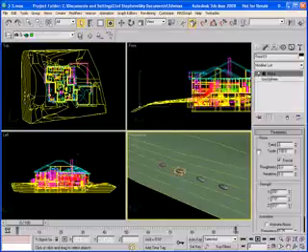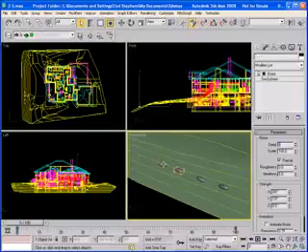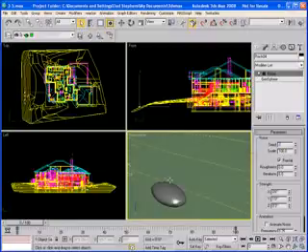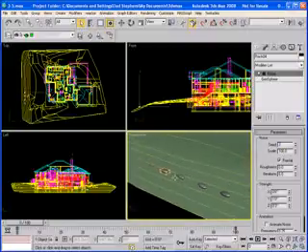Under seed, we'll give this a different number. So seed of 2. Again, you can see it shift there, so it's just randomizing that noise. And for rock 4, I'm going to go seed 3, and again, randomizing that one also. So seed is basically just a way to change the noise that's being applied to an object.